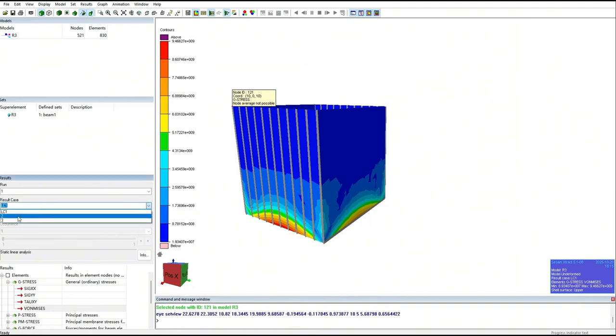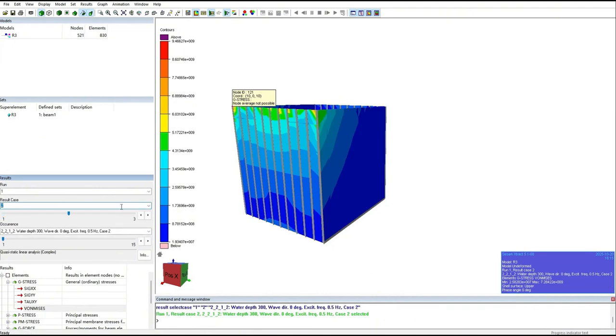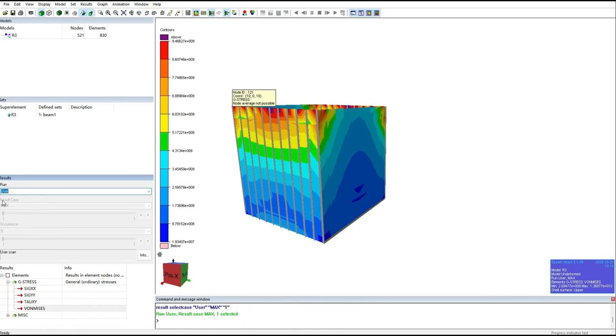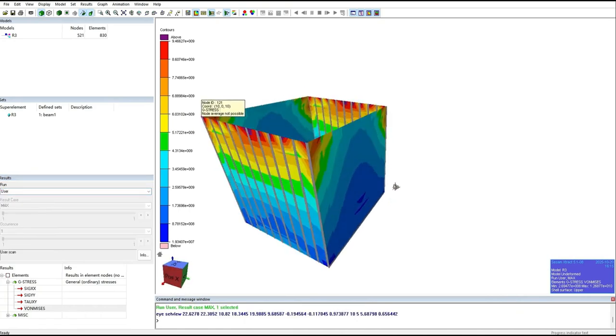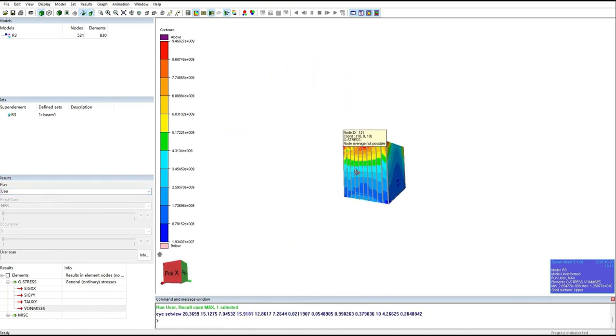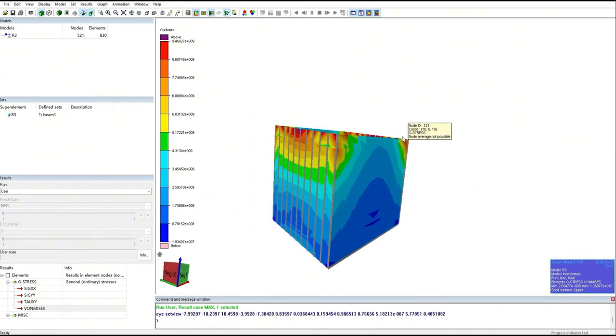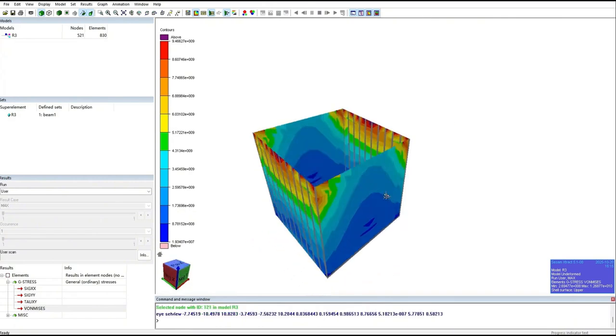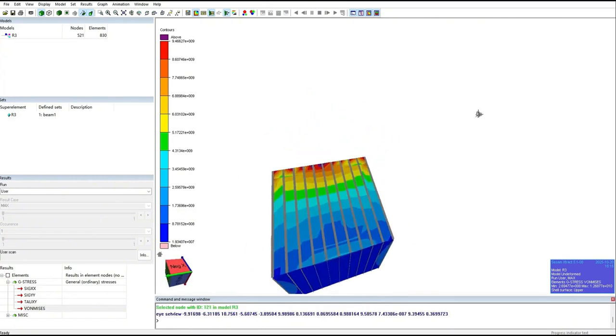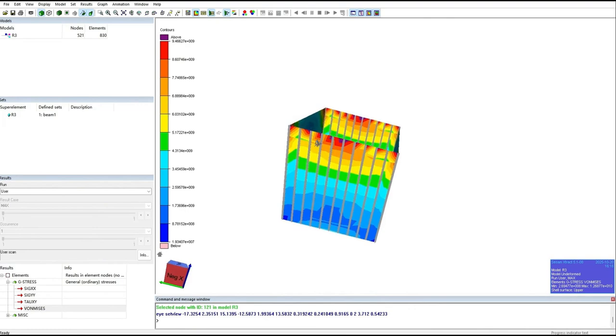After clicking, we can see one here on the left. I just entered one. The U here is the maximum value that was scanned. That is, the maximum von Mises stress value on each mesh under all your working conditions. Of course, the minimum value is obtained in the same way.